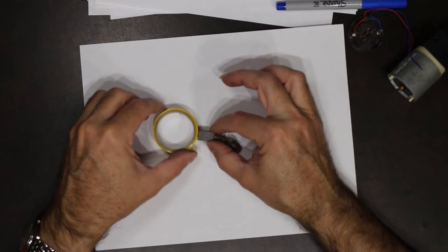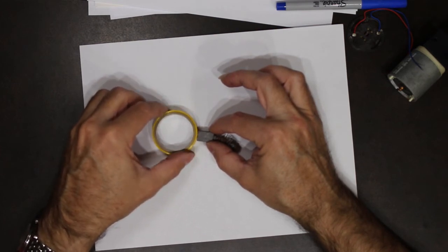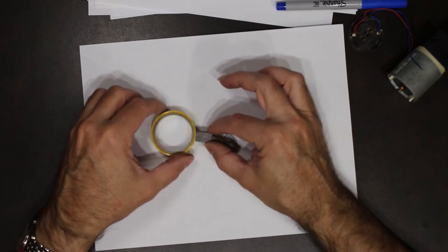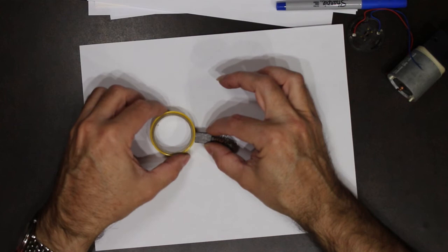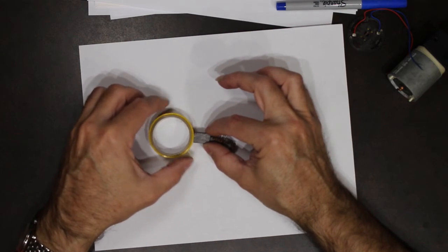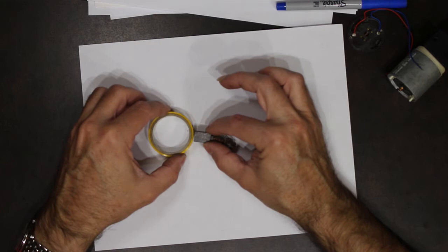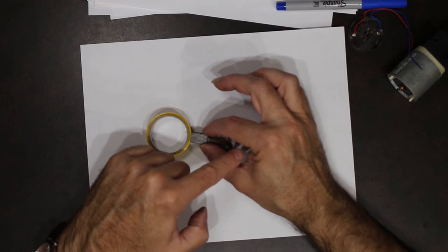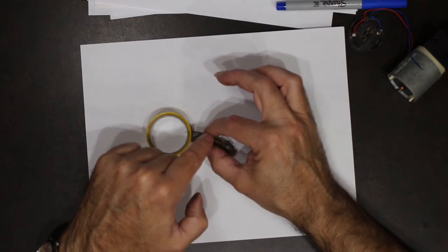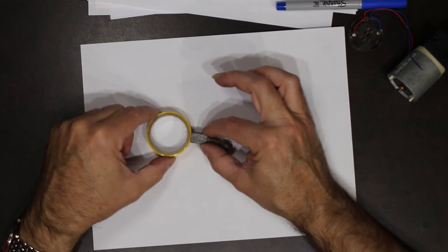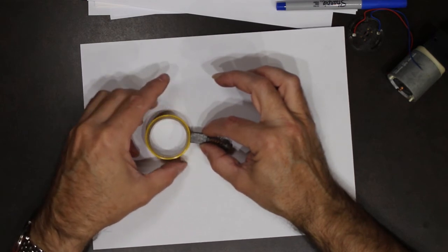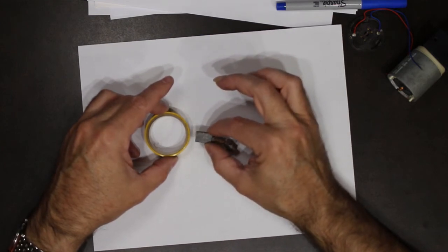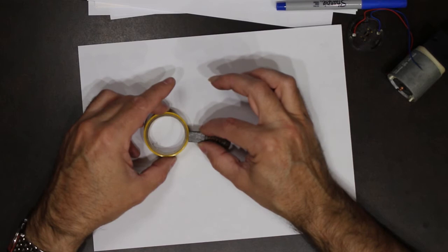The ring is allowed to rotate with the motor, but notice how the brush does not move. The ring rotates as the motor spins, keeping a constant pressure with the spring, so electricity is fed from this end, through the spring, through the brush, to the slip ring. So the slip ring can spin, and the wires outside stay in one location and don't get twisted.